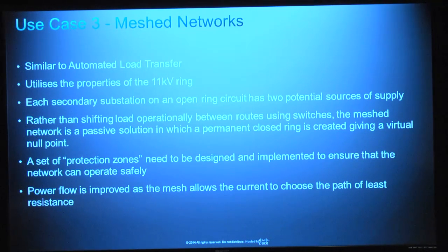Now, for any of you here who are a protection background, you will know that protection requires a very low latency performing network. WiMAX is not a low latency technology, certainly not in that 0 to 10 millisecond range. So what they have done is they've engineered far more conservative protection schemes where they're more tolerant of longer latencies in order to allow for the delay or the latency within a WiMAX infrastructure.